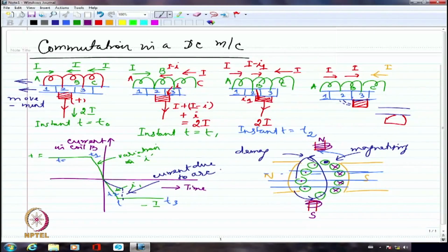This is the demagnetizing effect, which is actually made near the interpolar region. This is opposing whatever is the direction of current here, the flux lines here. The field lines are from this north pole to south pole, whereas this line is in the opposite sense. But if I have a north pole here, this will strengthen the magnetic field here, which will try to orient itself towards the north more, right? Previously, this conductor was orienting itself towards the south pole because essentially the neutral axis itself had shifted.